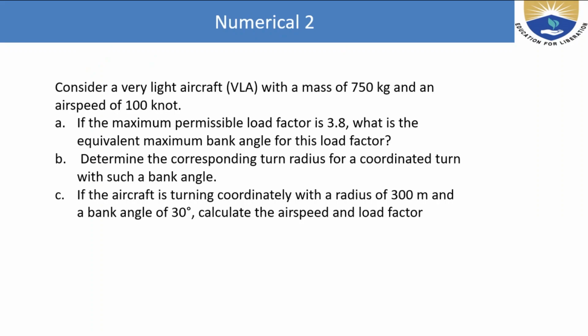Now we have to solve this problem. Here, the first problem, if you see in the problem, we have to find the bank angle. So here the load factor is given, n is equal to 3.8, and we find phi.